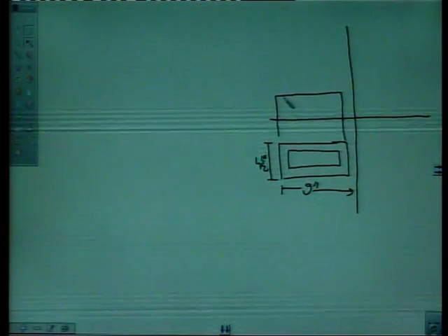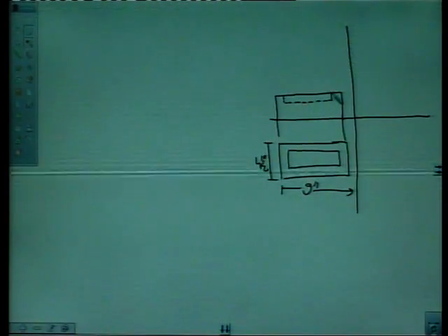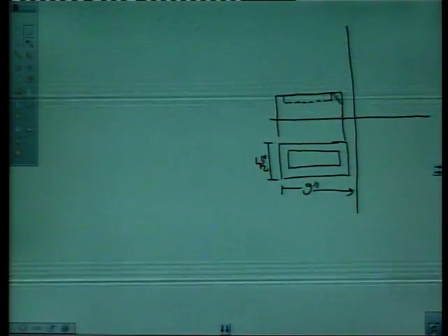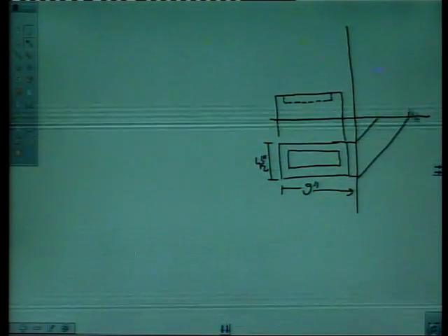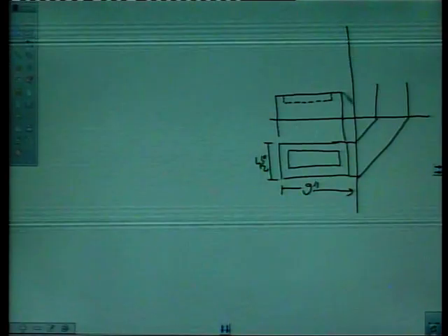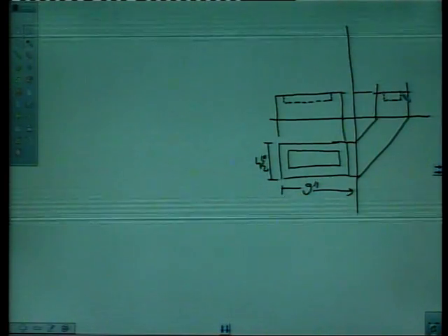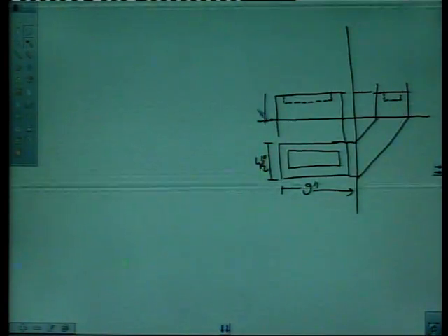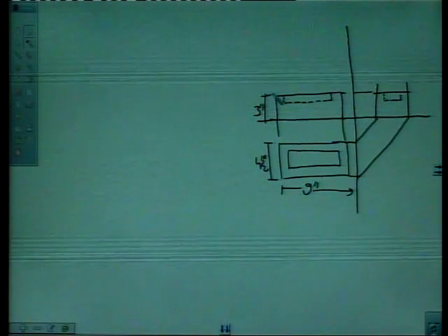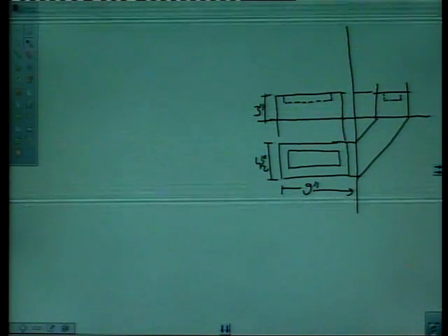In elevation I will draw quickly, as you all know what are plan, elevation and side elevation. Guidelines. Frog will be dotted in elevation, right? And in side elevation also, like this, 45 degrees. I am not going into detail how to draw orthographic. You all know how to draw it, right? Say height of the brick is 3 inches, standard brick. Now how to draw its isometric again, step by step.